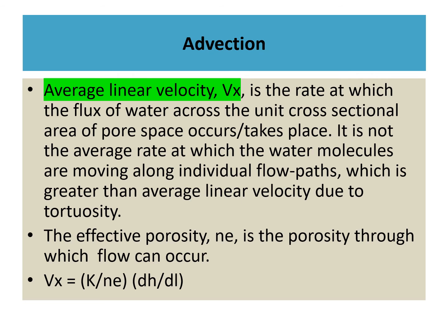This is the hydraulic conductivity, and this is the hydraulic gradient. Both will be multiplied, and divided by the effective porosity, which accounts only for the connected, interconnected pores.